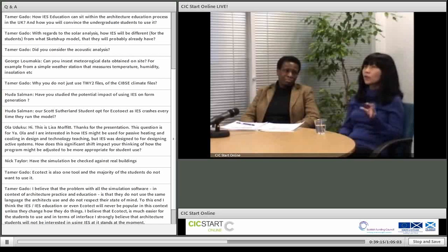But in the VE climate database, you have to have a certain format. You normally have to have the 6 parameters. For absent parameters, unfortunately, you have to fill in with default data if you don't have it. The answer is yes.